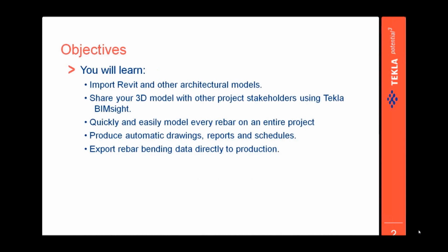We're going to show how you can use BIMsight to share your data-rich 3D model with the contractor, the architect and the engineer to collaborate on the project. We're going to show how easy it is to model reinforcement within Tekla. We're going to produce automatic drawings and scheduling, and especially scheduling that goes direct to machinery through the BVBS export.